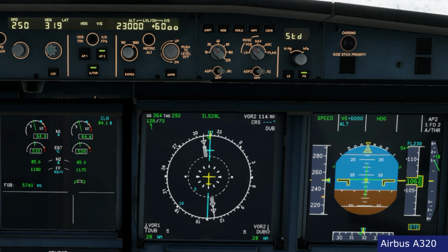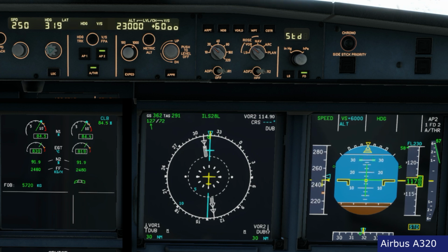Same as any other aircraft, what happens is that the autopilot attempts to maintain the selected vertical speed, because as a matter of fact the speed is an output, the automatic control of speed is an output. So you see that of course the auto thrust gives us the climb thrust, which now is 84.7, but despite having the climb thrust set, there's not much the auto thrust can do. We start losing the speed in the attempt of maintaining the vertical speed.